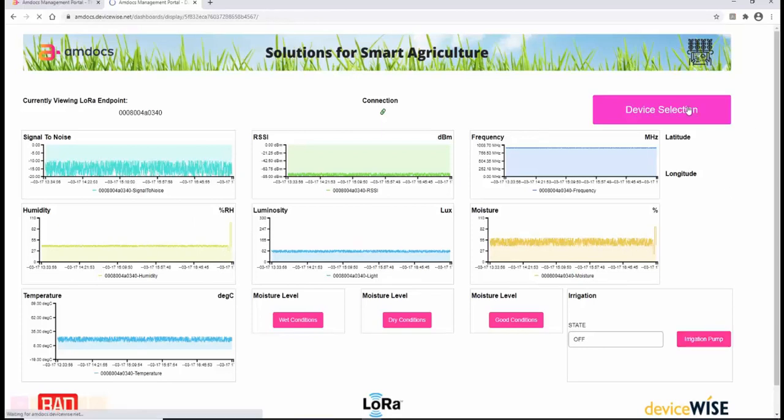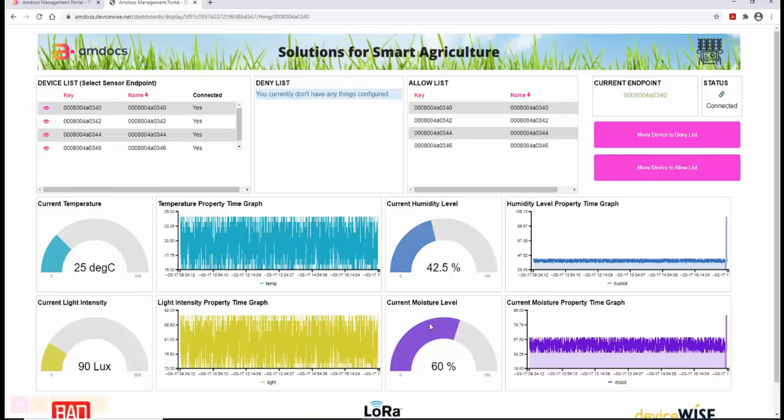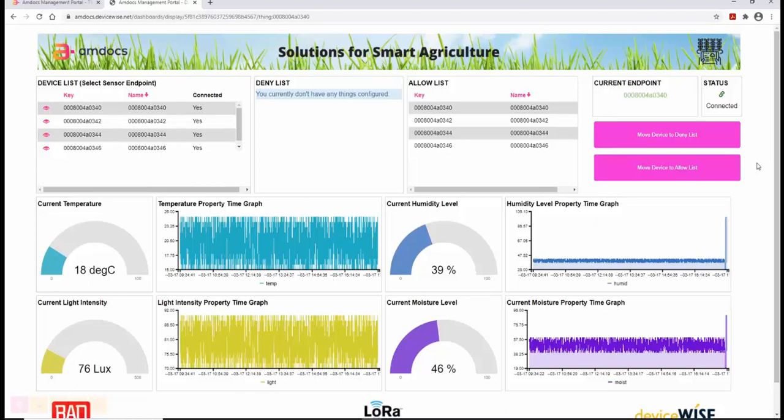If we go back out and take a look at the system, go look at that specific sensor area, we can see that things are back under control. Our current moisture level is around 6% in the field. Our humidity level is back in the low 40s. Ambient temperature and luminosity are there as well for the time of day that we're showing. So that basically showed a basic overview of the operations, getting the live signals from the sensory level, controlling the moisture and such by way of actuating the irrigation pump system.